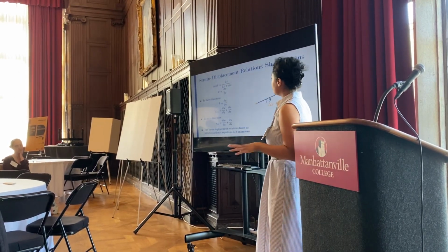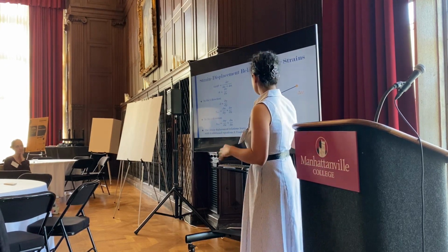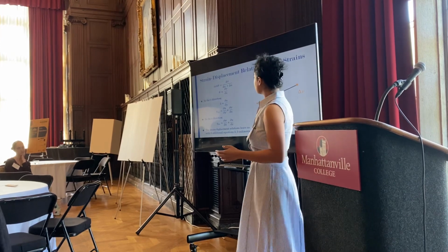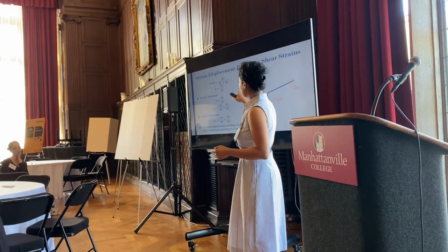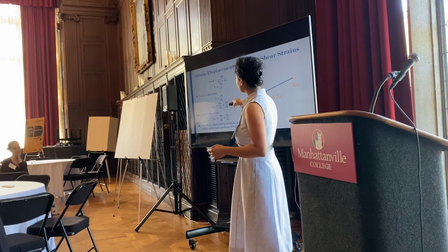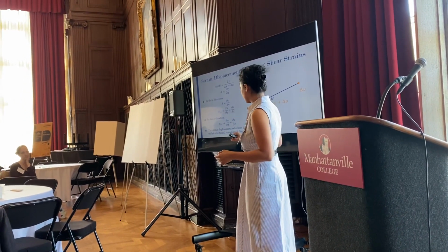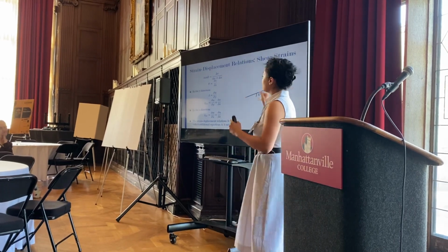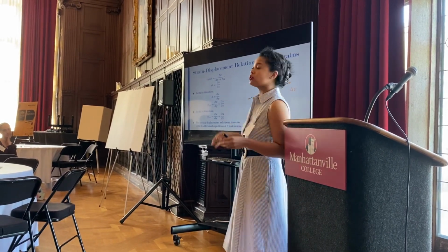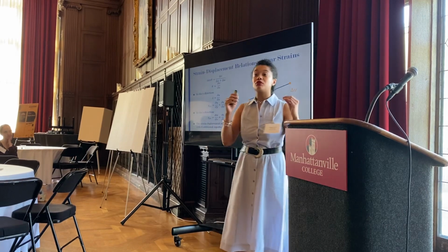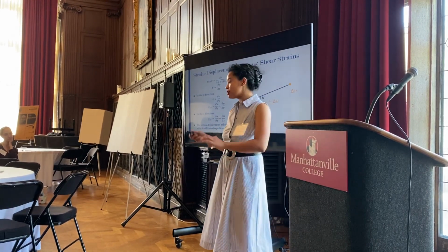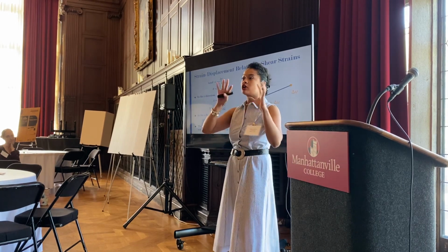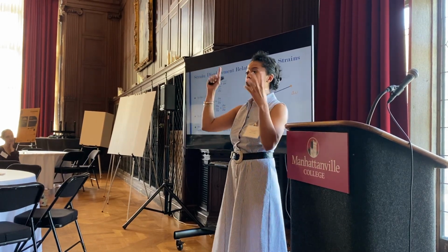Next, we have our shear strains and the strain displacement relations. So earlier we talked about skewing and our angular displacement. These angular displacements are found to be equal to gradients as well, and when you sum those gradients, you get our shear strain. And the same is true in the x direction and in the z direction. So, based on the last slide and this slide, we have 6 additional equations and 3 unknowns. That leaves us with 15 equations and 15 unknowns, which ANSYS does not take directly. It puts it into a weighted integral form to solve for each singular node or point.